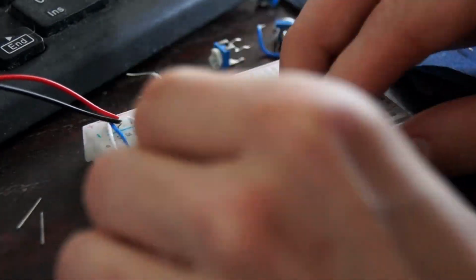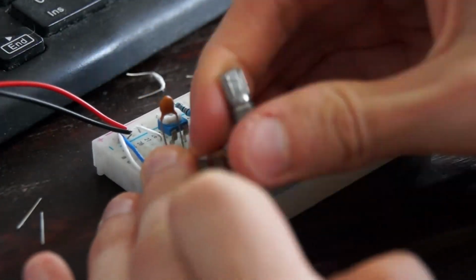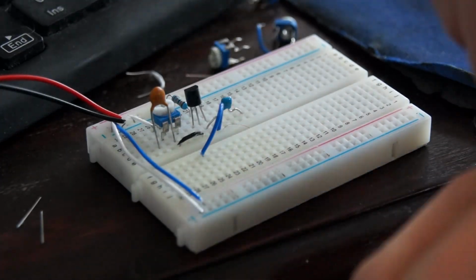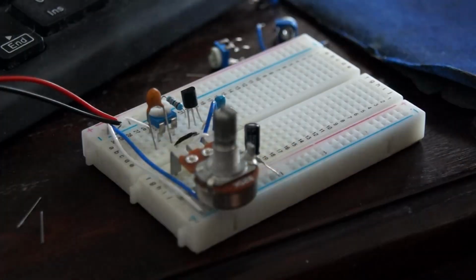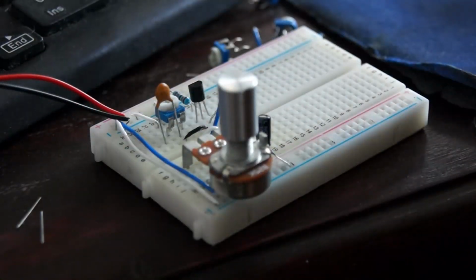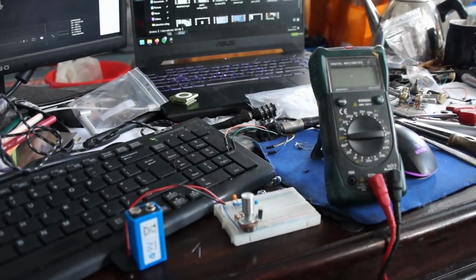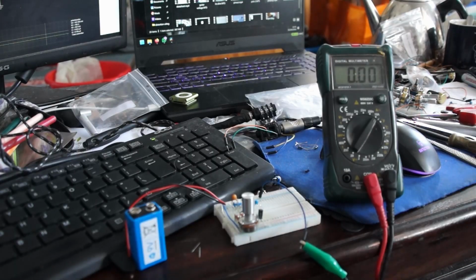So I'm doing a voiceover over a time-lapse of me assembling the preamplifier. Here you see me setting up the gain, and remember that since the polarization is reversed, you should put the minus of the capacitor to the circuit. And here I set up the bias measurement.